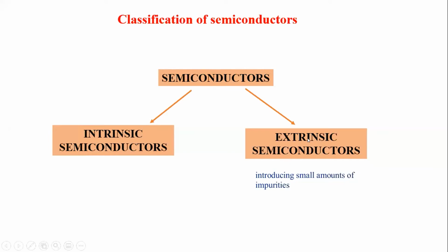And then if you add some other material or foreign element to a host in very small percentages, normally we call them parts per million. The number of atoms per million host atoms is called parts per million, or you can say it in terms of atomic percentage. If you know it, you can calculate and add it during the growth itself or after the growth too. These are added to change the character of the host to something we want.